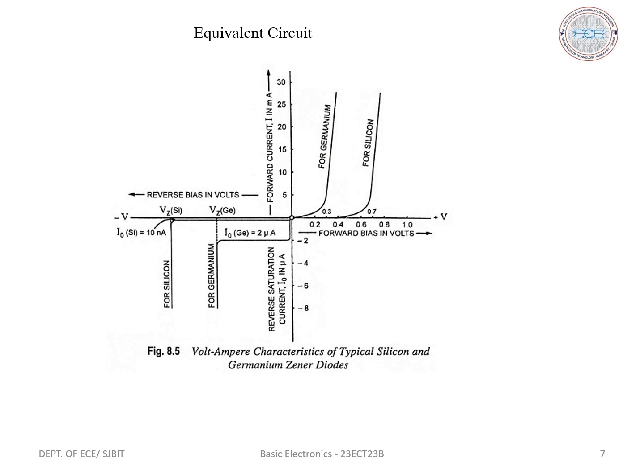Next, the equivalent circuit. First we will check the biasing of a Zener diode as well as the VI characteristics of a Zener diode. First we consider forward biasing of a Zener diode. Where the anode of the Zener diode is connected to the positive terminal of the DC source and the cathode is connected to the negative terminal, the Zener is said to be forward biased. A forward biased Zener diode behaves identically to a forward biased diode. The forward characteristics of a Zener diode are shown in this figure. It is almost identical to the forward characteristics of a PN junction diode.